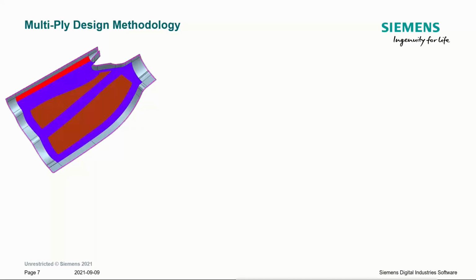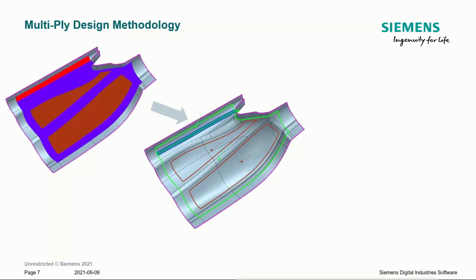We have different parts of the tool surface that have different laminate specifications, meaning they have different materials of different orientations, may have core, different numbers of plies, and that's going to be used by Fibersim. So the only geometry requirement is to build this geometry to define the zones. And then Fibersim is going to generate all the engineering layers as well as all the ply layers, ply boundaries based upon that. So if I have an area of thicker to thinner, it's going to build the number of transitions necessary to transition between those two different areas automatically. If I go back and change the specification at the zone level, it will remove those layers when I run the zone layer function again. So everything is going to stay linked and associative.